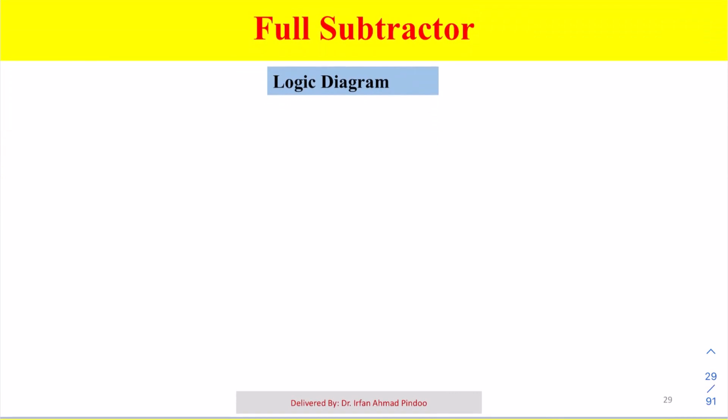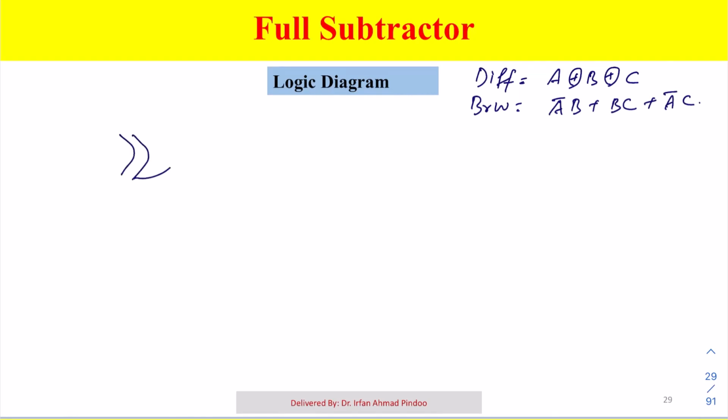So finally, the last step of our design procedure is the logic diagram. Before we go to the logic diagram, let us revise 2 points. The difference equation was A XOR B XOR C, and the borrow equation was A bar B plus BC plus A bar C. Now as far as the diagram is concerned, we can have a diagram like this for our difference first of all.